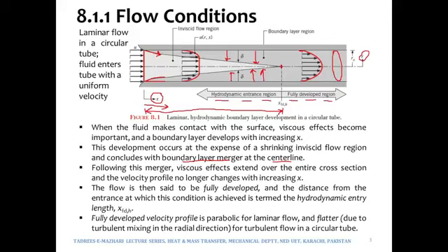So the velocities at each and every point all around 360 degrees on the inner surface of the pipe, the layers which are in direct contact with the pipe inner surface would have the same velocity as that of the pipe. So if the pipe is at rest, the velocity of the layers of fluid at 360 degrees on the inner surface of the pipe would also be 0.